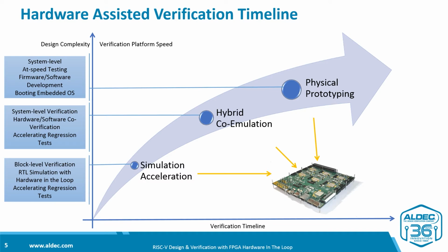Now I have good news. Hardware-assisted verification can help to tackle many of these presented challenges. Due to the availability of high-density FPGAs like Xilinx UltraScale US440 and their adoption for emulation, it's possible to hook these versatile devices into the verification environment and use them as a vehicle for implementing highly accurate SoC models.